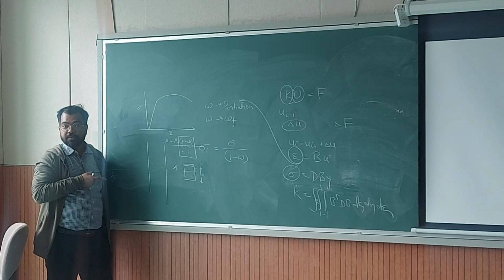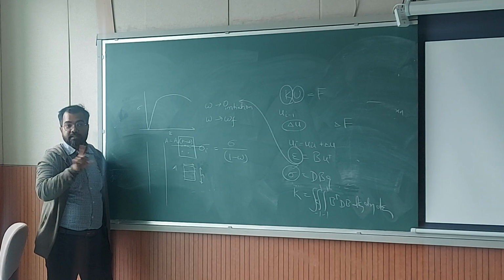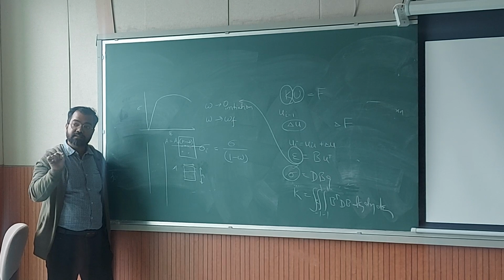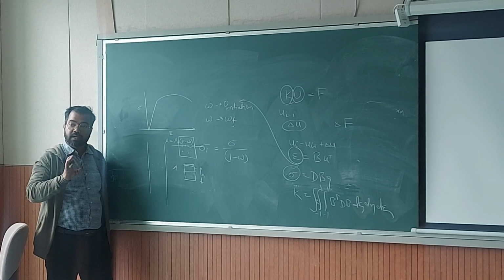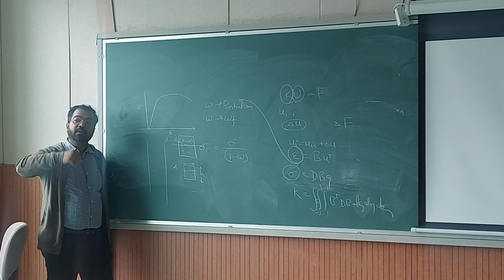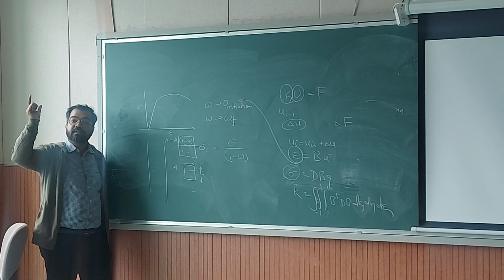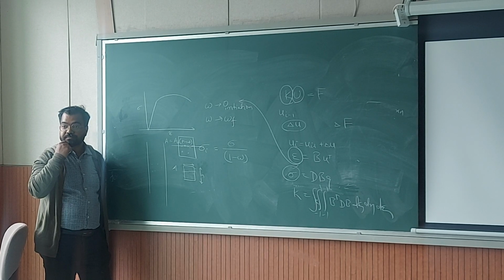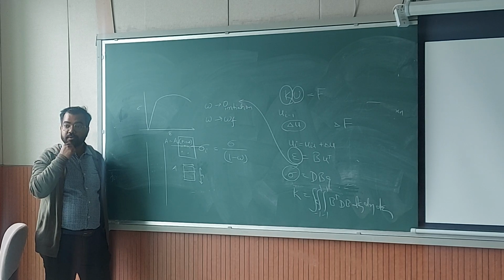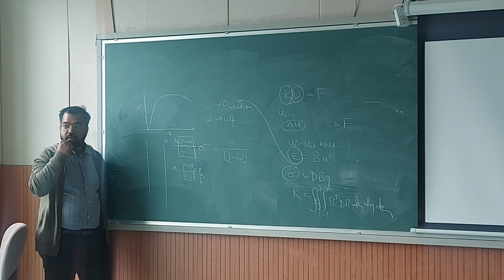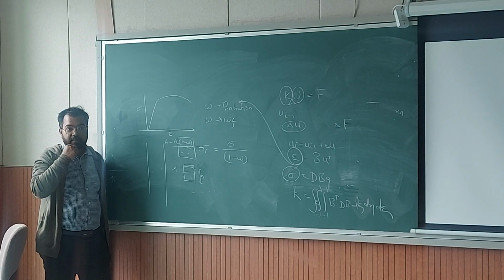If you don't have damage in your formulation, if you just have quadrilateral elements with elasticity and plasticity, and then you run the code, and then you apply whatever displacement you want to apply, your sample will keep on elongating till eternity. Well, not till eternity, because the convergence will fail. Okay, so there will be no solution after some time, and your code will just get aborted. Okay, but no necking will happen.